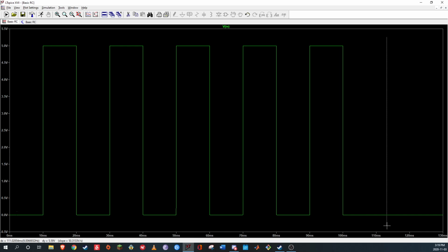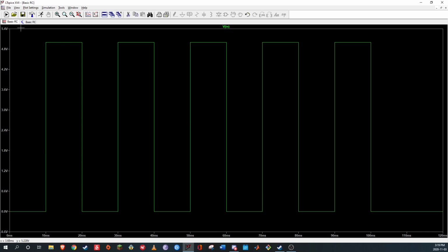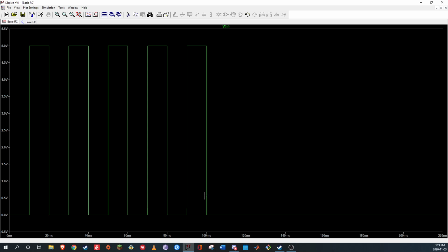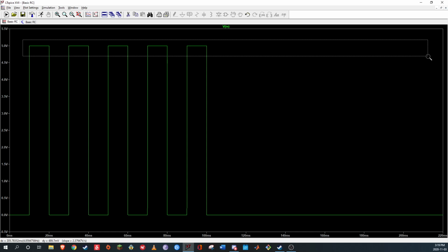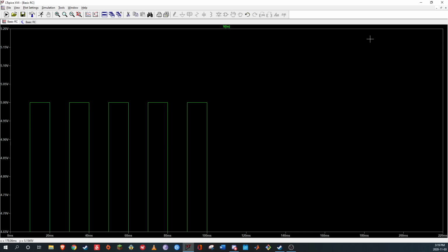That can be tricky when you have very small signals with super tiny ripples or even huge ripples. So you may have to zoom and play with your limits just to see things. If I make this box really long, it can zoom in on just the top.